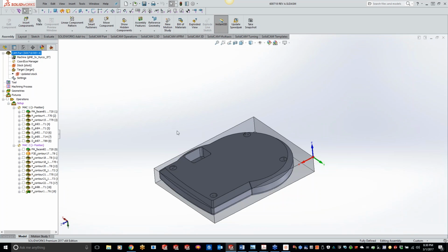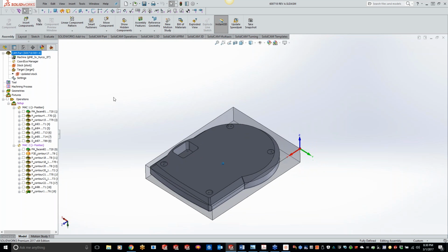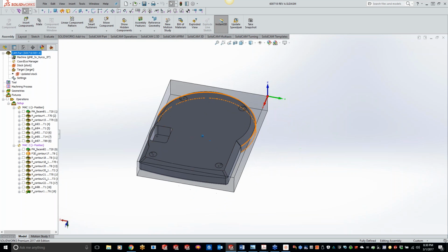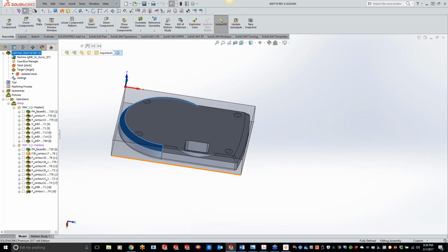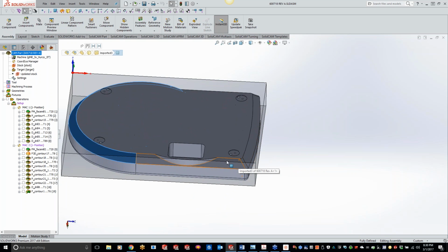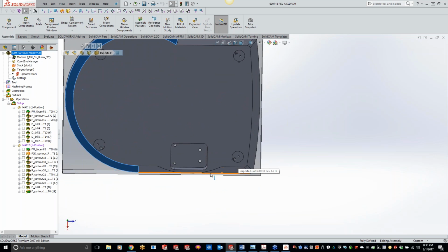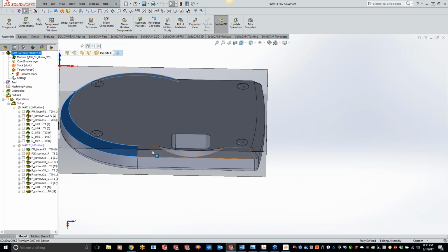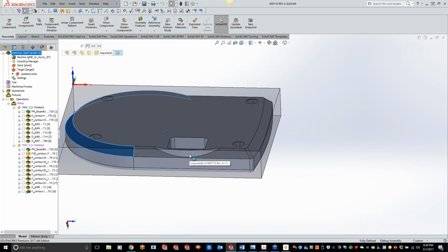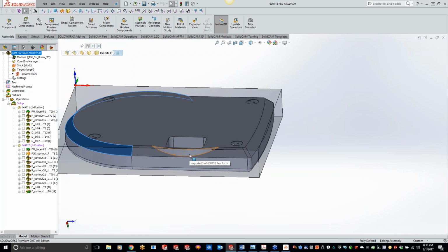Okay. Now, this particular part right here, I pretty much have it all machined, but the big kicker here is this outside taper. One thing I ran into with the customer is he wanted to go along and use the side of the end mill, if I get a straight down shot here for you guys, to come up here and then start cutting into the radius again down here, or the chamfer. So a little bit tricky, but this is exactly what the HSM boundary cut was meant for.